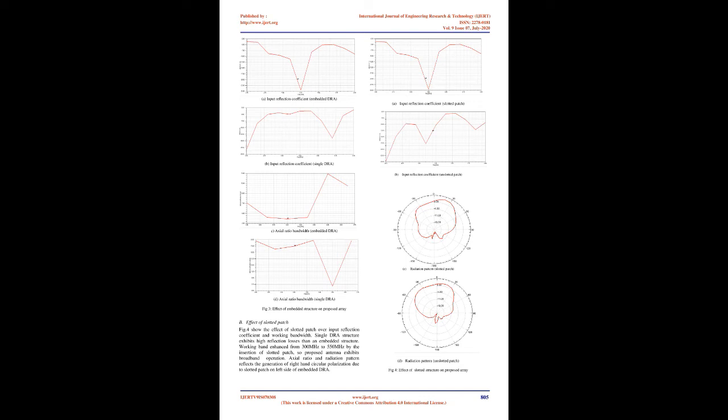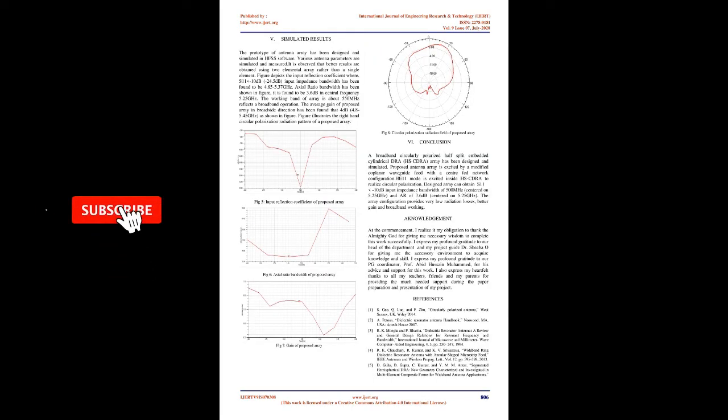Step 3. Apply a patch inside the embedded DRA and create a symmetrical patch with bilateral symmetry. Calculation of patch parameters is by surface modulation, similar to a normal patch. Design equations are used with an additional constraint of 1 < L/W < 1.5.